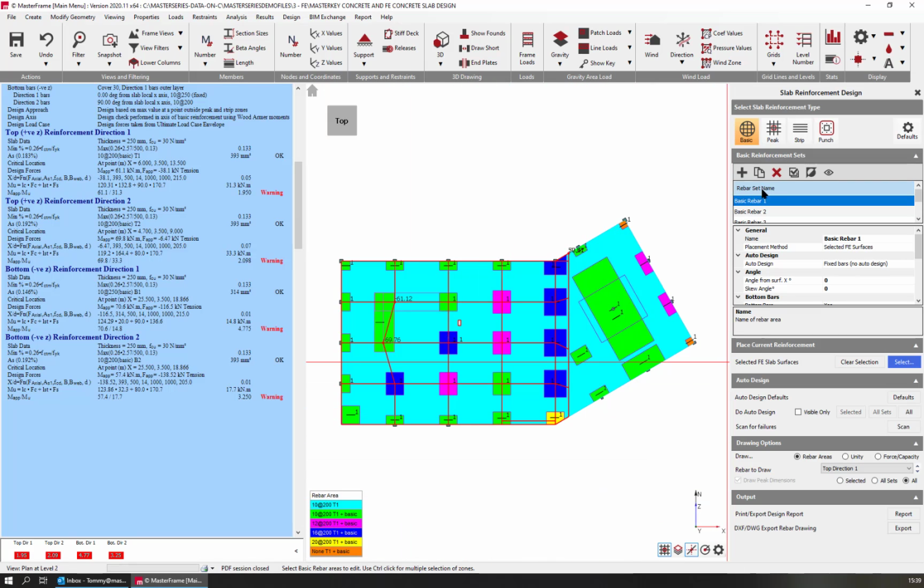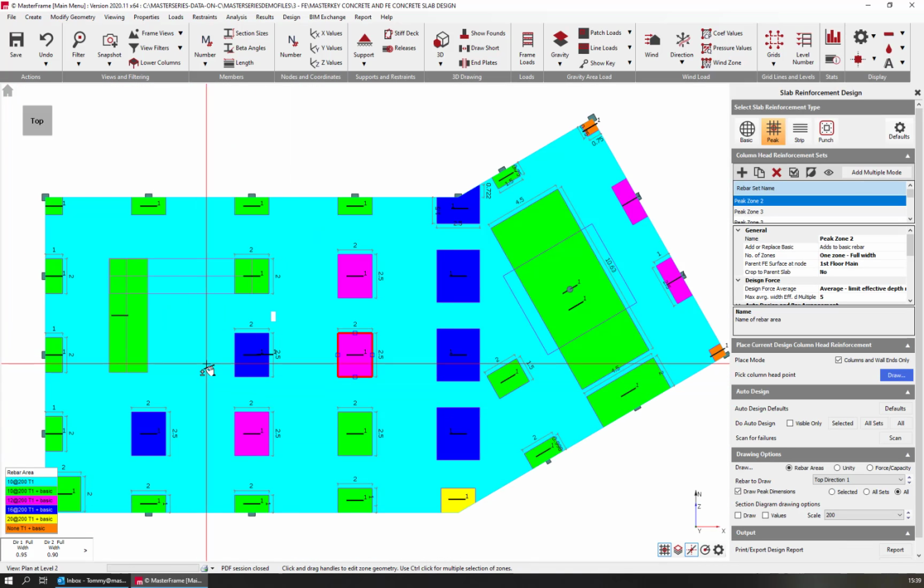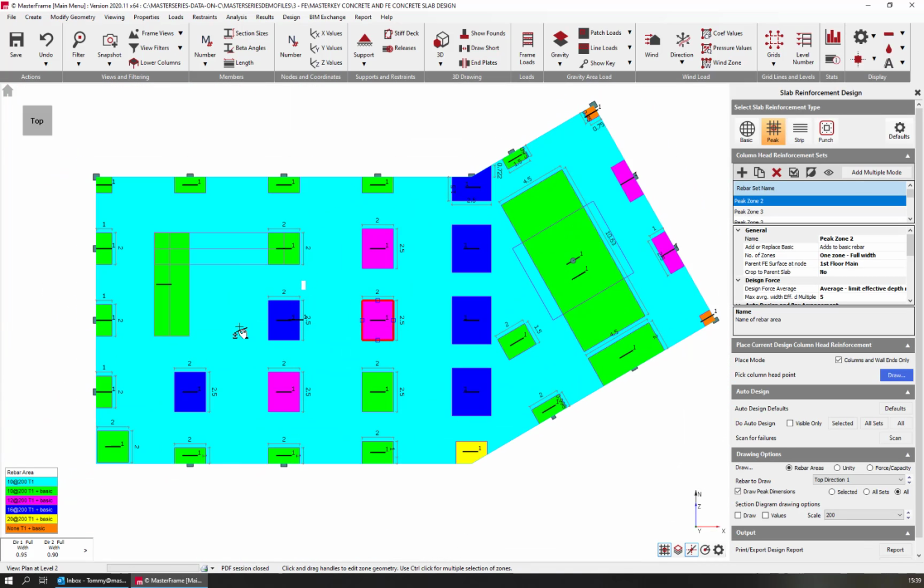We can see the rebar, and we can see all the dimensions of the rebar, and we can actually even collapse this just to give ourselves a wee bit more room to work on this, and we can see the dimensions of these. And first of all, I look at dimensions, and then I look at the reinforcement. 12s at 200 here. These are 16s at 200.